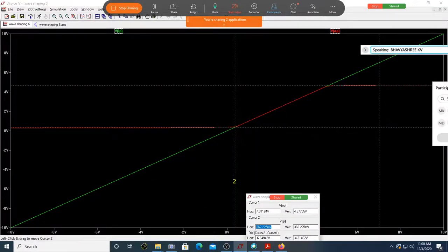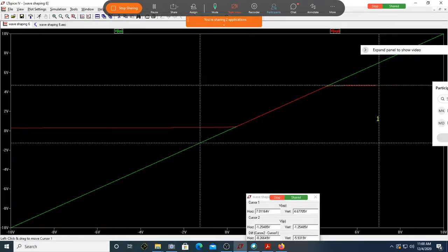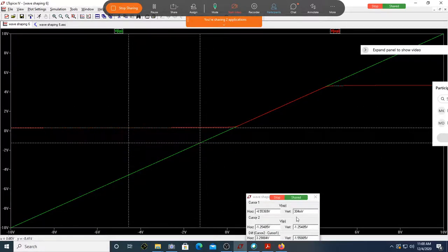Can you see here what is the voltage? Okay, let me just put it on the. Can you see how much is that? 304 millivolt. That is 0.3 volt. Yes, sir. 0.3 volt is coming from 1 minus 0.7. 1 volt is your reference, minus 0.7 is your cut-in voltage, which is put in the opposite direction.